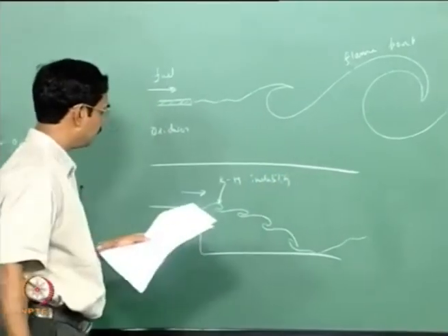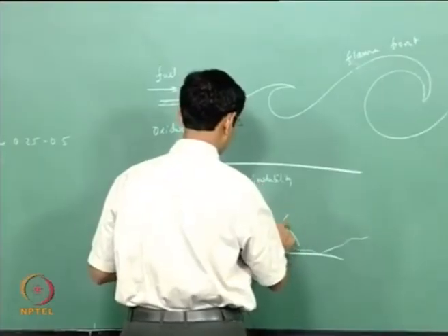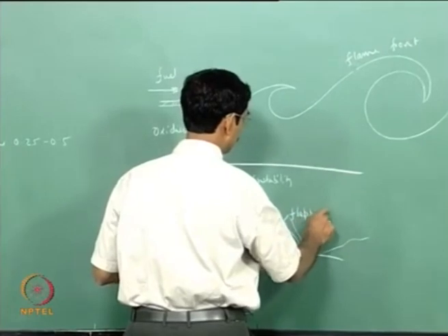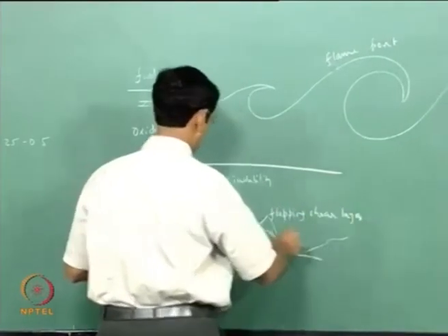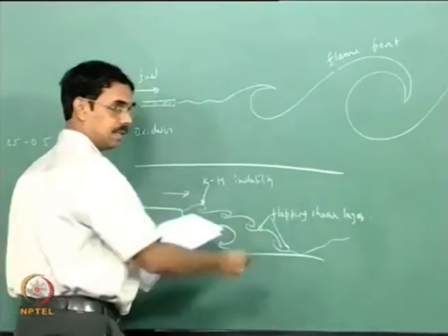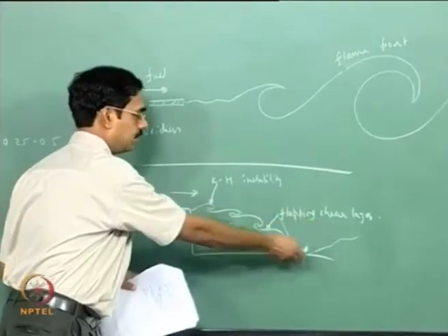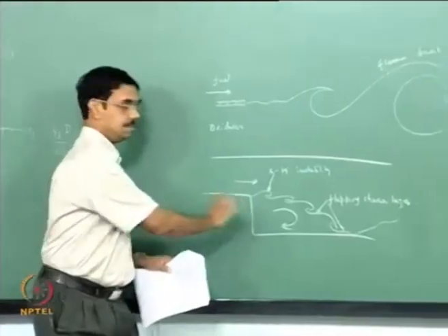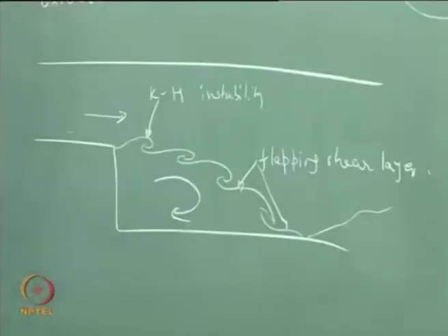In fluid mechanics people often call it KH instability, and then you can also have this flapping shear layer, and that's another kind of instability. It can start off with the KH instability, but then you have the step instability. This is for low steps, when the step size is low. If it is very big, then this won't happen. You just roll up without interacting with the vortices.